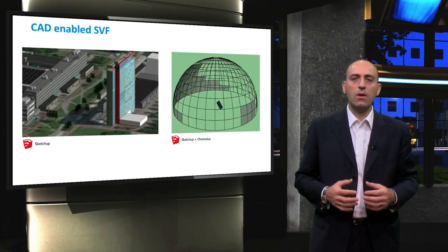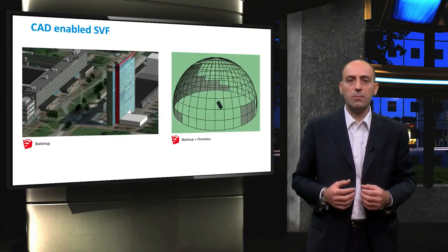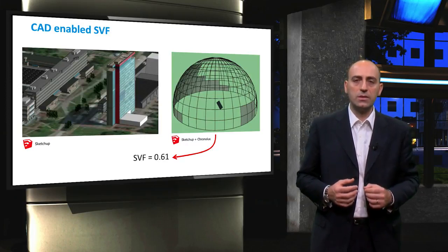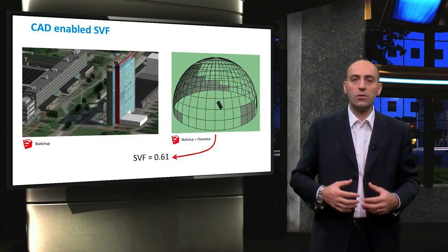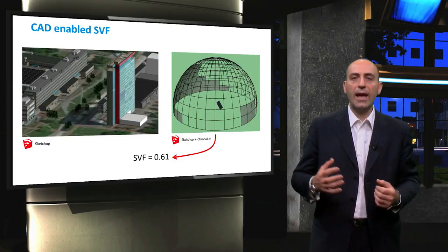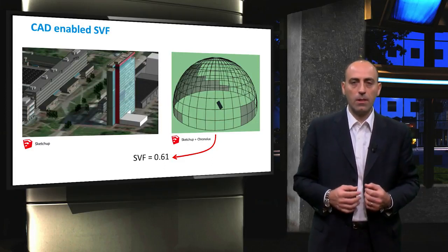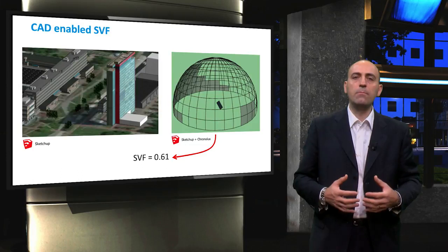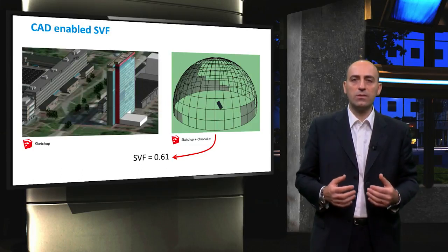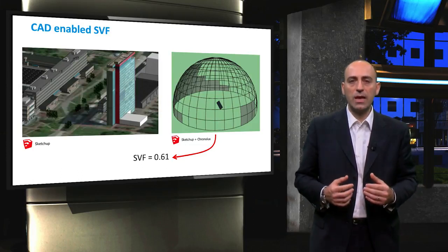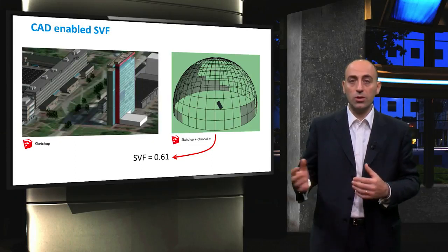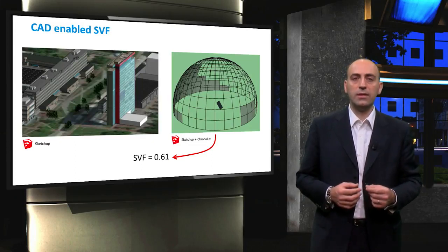With this method, for the above location in TU Delft, the Skyview factor of the PV system was found to be 0.61. This is obtained after considering both the tilt angle and the surroundings of the PV system. For comparison, when the same PV system was placed in a free horizon scenario, its corresponding Skyview factor obtained through the equation approach was found to be 0.82.